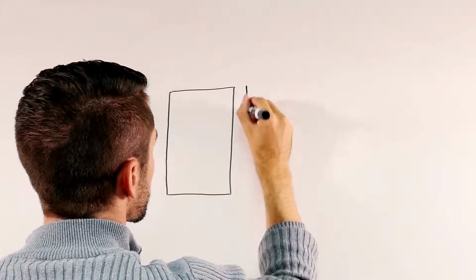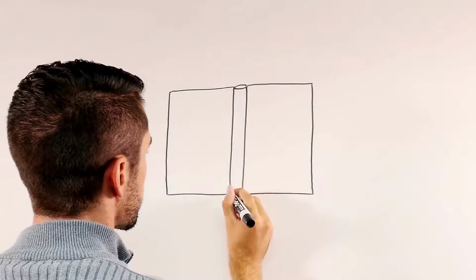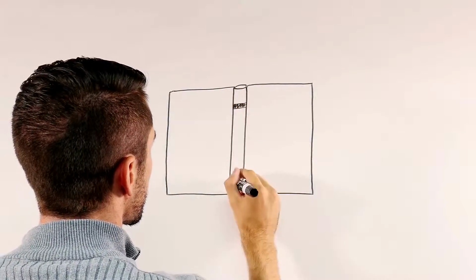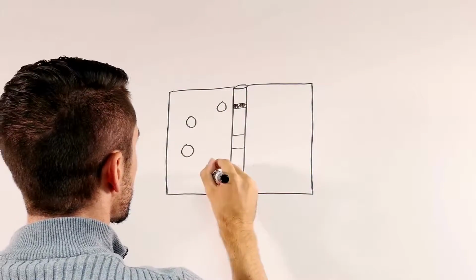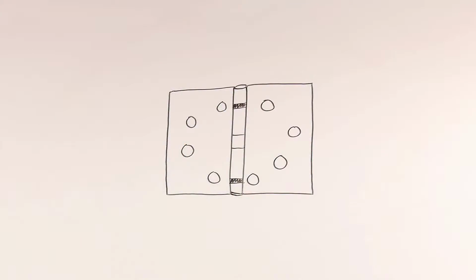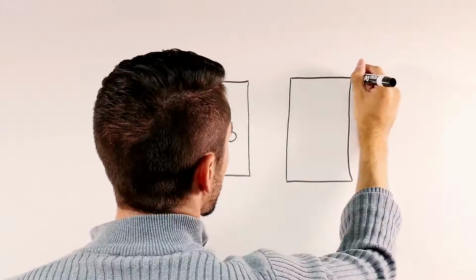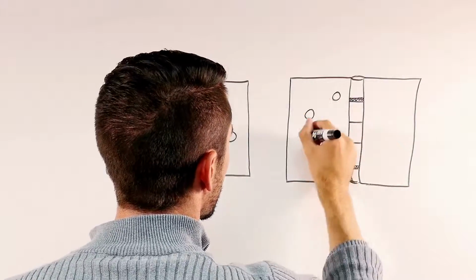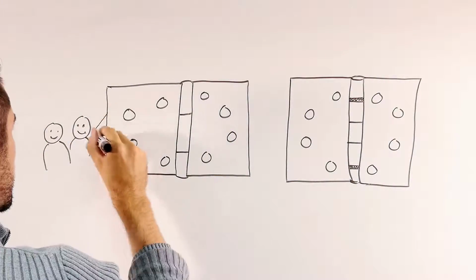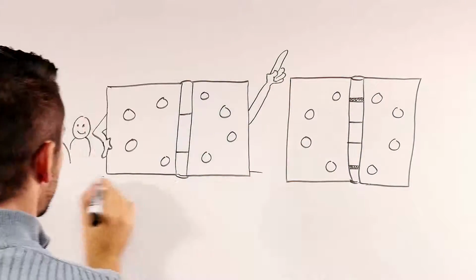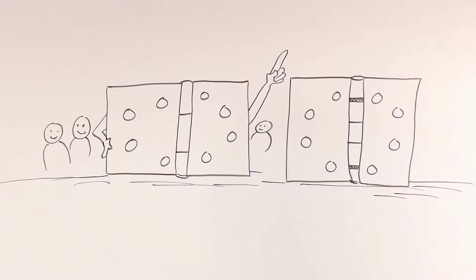Conventional hinges, also known as butt hinges, are simply two metal plates, also called leaves, joined by a pin and a knuckled barrel. The pin has a tip that keeps the pin from sliding down and out of the barrel. Many hinges are constructed with bearings in the knuckles to provide for a smooth and consistent operation. The number of knuckles that form the barrel is one of the primary characteristics of conventional hinges. 5-knuckle hinges are the most common. 3-knuckle hinges are also well liked because they are considered more attractive because of their cleaner lines.